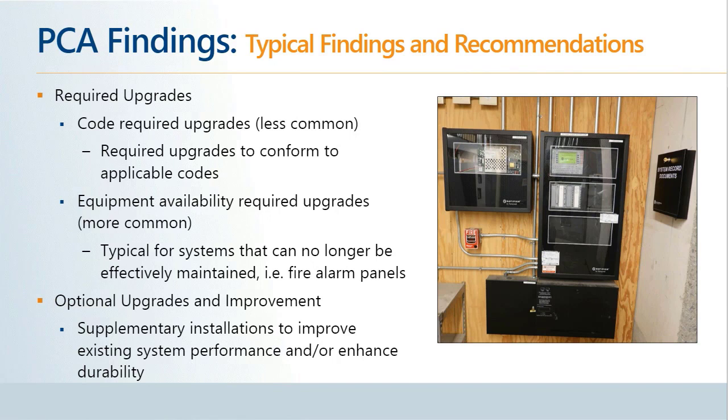While this is not required for the parking garage to function in its primary capacity, the installation of this type of coating can significantly eliminate deterioration potential for the concrete slab. Essentially, this is an investment that's made to reduce potentially expensive future concrete repairs.